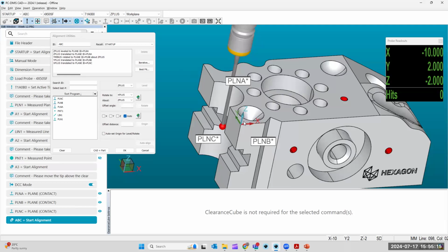So you have to think about your datum precedence. You have to understand datum precedence. And maybe if you don't understand it, complete the datum precedence table, because then you at least understand which origin should be constrained by what, and which axis is this. In this example, A is constraining Z, B is constraining the Y, and C is constraining the X. So we know that triad is in the correct corner.